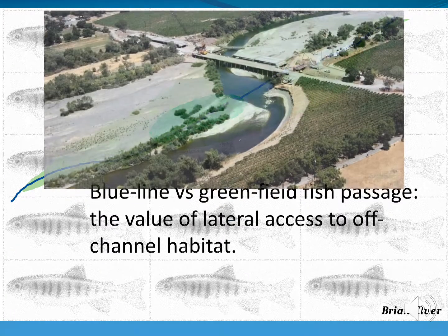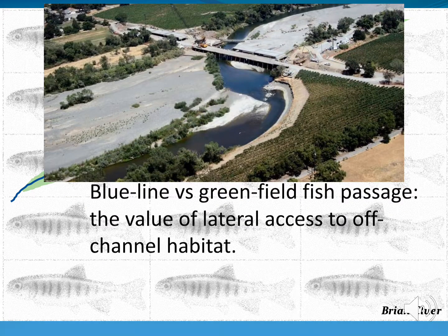Can your stream crossing affect greenfield fish passage? And I would say yes. If you go back to the Russian River example here, where you sort of lock the channel in over here, we've decreased our overbank duration and frequency of flooding, as well as really going to alter what this habitat out here looks like if it doesn't routinely receive flow and the channel moving back and forth.